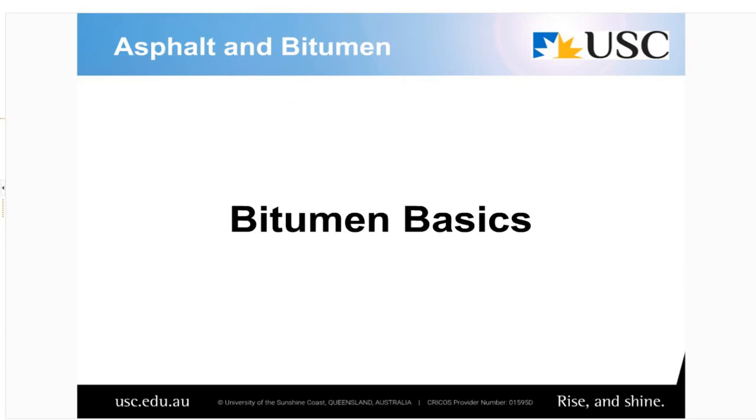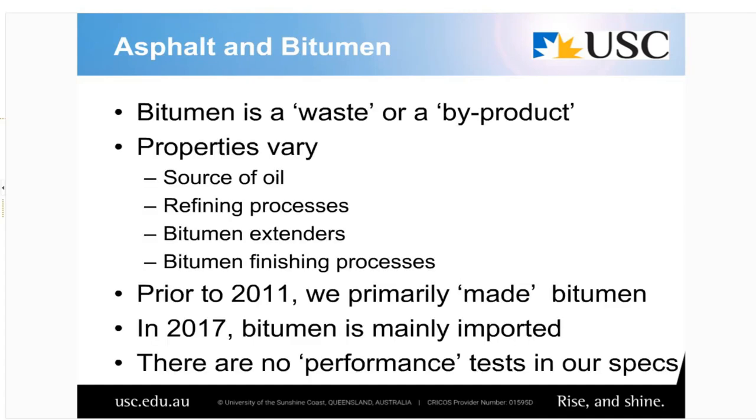So that covers how we commonly use bitumen in our pavements, and again, not specific to airports, but certainly applicable to the airport context. In terms of some of the, almost if you like, myths and facts about bitumen, the reality is that bitumen is a byproduct of producing high-value products like LPG and fuel and diesel and jet fuel out of crude oil.